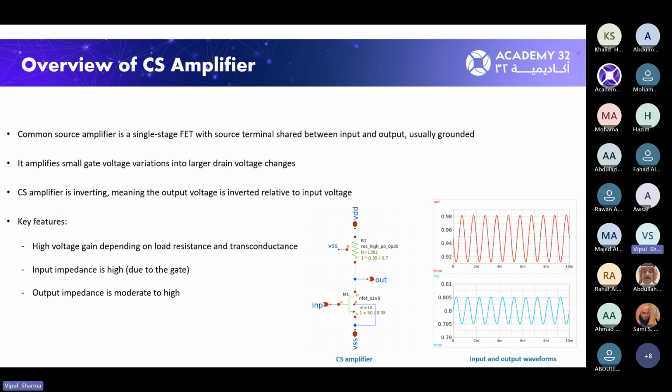But it is an amplified one, depending on the transconductance of this input transistor stage and also the value of the load resistance. So all those criteria need to be taken care of whenever you're designing any circuit. As a designer, the requirement is that you want to design a 15 dB single stage amplifier. So you need to tune the W by L of these transistors, what will be the gate voltage, how much overdrive is required, how much will be the GM, and how much load resistance needs to be used. Based on that, your gain properties will be decided.